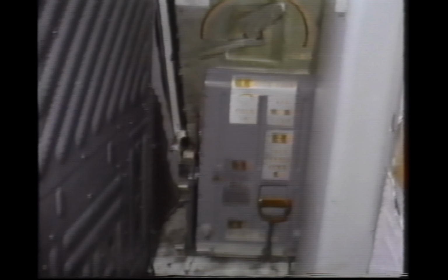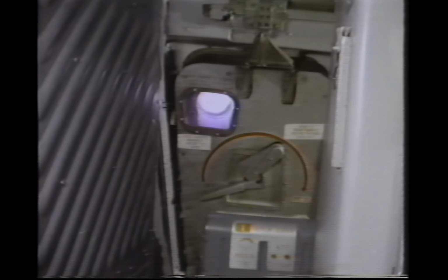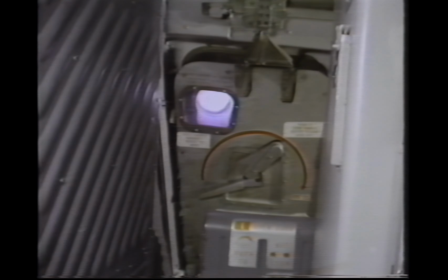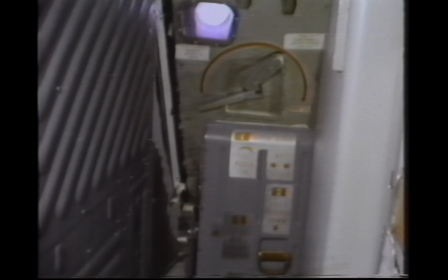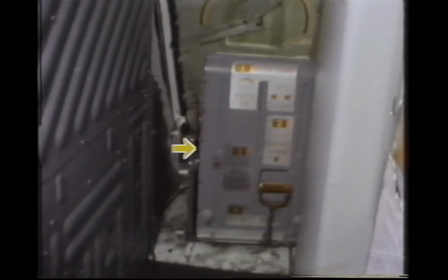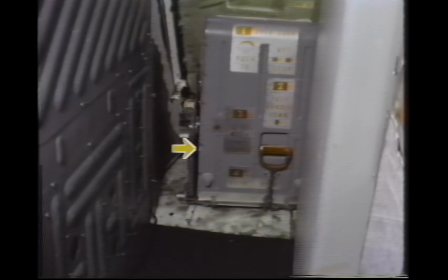Let's take a look at the crew service door and evacuation slide. The engineer is responsible for pre-flight items on this door. They are crew service door closed with operating handle in the closed position, the evacuation slide in the ready position in front of the door, and the slide retaining latch engaged in the floor track, the red release handle in the stowed position, and the slide inflation bottle safety pin removed.